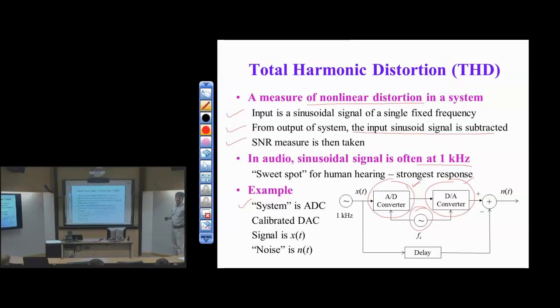When you're considering the SNR of the whole thing, do you just say I'm going to limit it by whichever one has the worst? So the question is, do I limit? If I remember, the system under test is the A to D converter, and I'm testing it with components that are more accurate than the A to D converter. Remember, a DAC can represent more bits than an A to D for the same. Yeah, no, in general, it's the worst case. It's like the weakest link in the chain, that same analogy, right? It's the weakest part of the system.